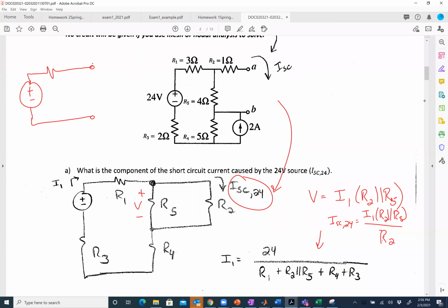If this is VOC, if I measure the voltage at these terminals, I'll see VOC. But if I then, at some time later, connect a resistor here, a current's going to flow. And what's going to happen to the size of the voltage that I measure here at VAB? Is it going to stay the same, or get bigger, or get smaller? It should get smaller because it sees resistance. VAB is always going to be VOC minus I times R Thevenin.